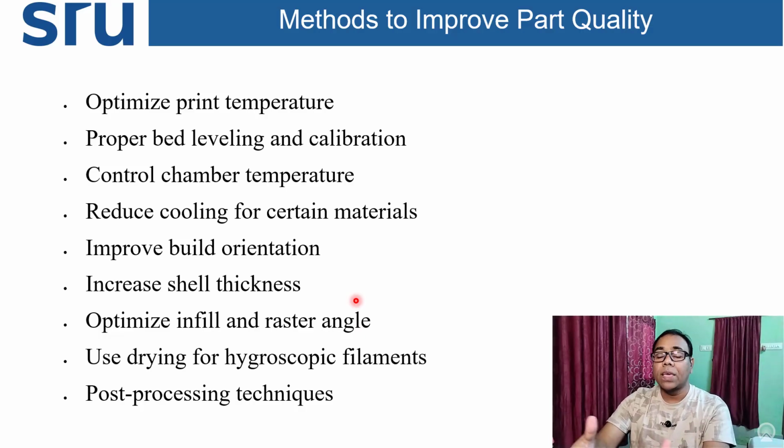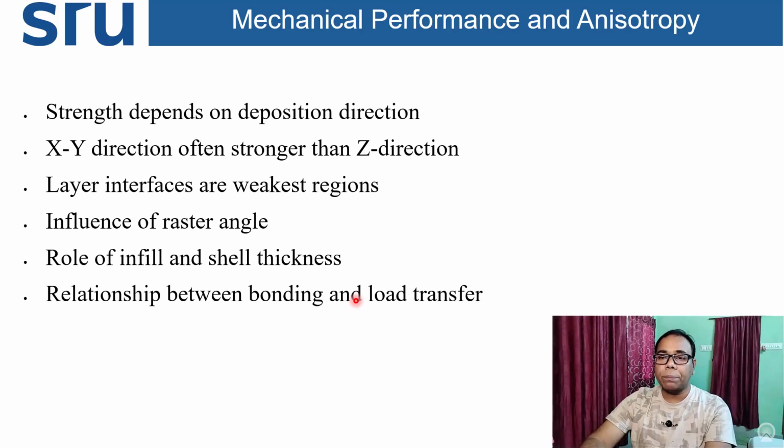Similarly, one can optimize the infill pattern, infill design, infill percentage or infill density, and raster angle. By changing these things, one can get better product quality. Sometimes we require post processing, or handling of hygroscopic filament effects. So these are the things one has to maintain.